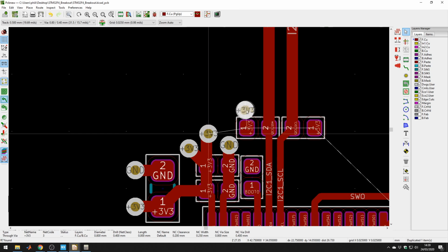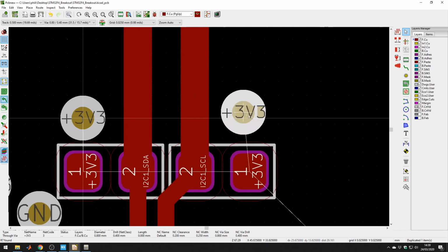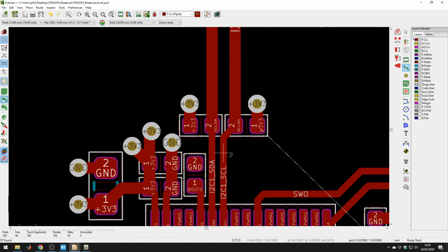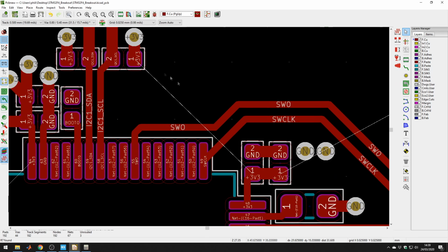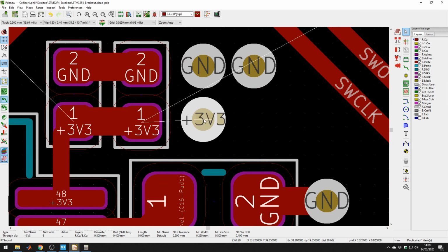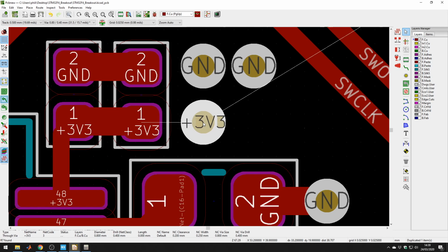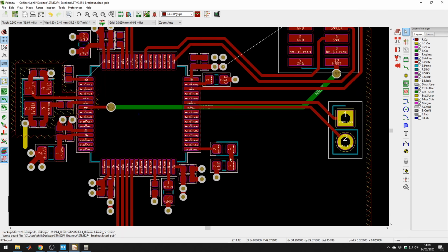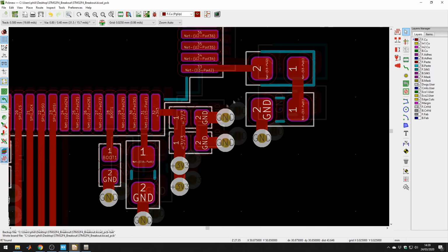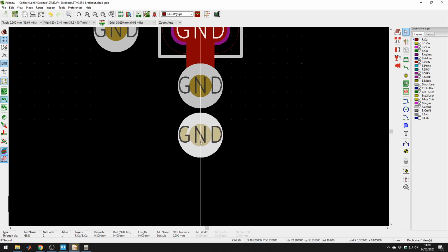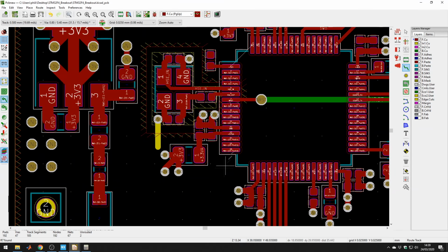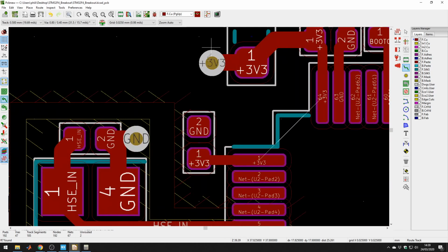Okay, we have here the pull-up resistors for the I2C lines. We just need one because it's just holding it at a constant voltage. And again, the same old thing: from the power plane through to the capacitor and then into the microcontroller. I think that's pretty neat. Okay, there we go. Have I missed something is the question. Yep, there we go.